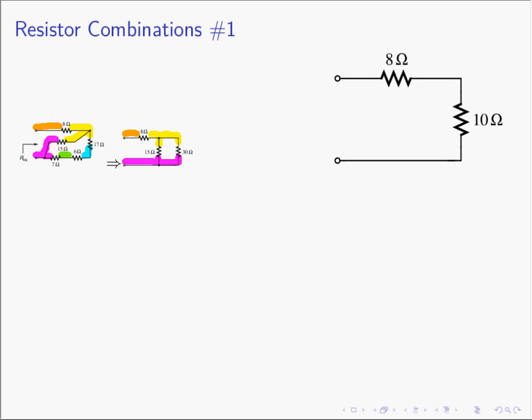In which case we have this circuit. So get our colored pencils back out again, and let's go on the other side of the 8 ohm resistor is yellow, and then this node there is kind of the pink. And if we look at this, we can see these are quite clearly going to be in series because any current that flows must go that way.